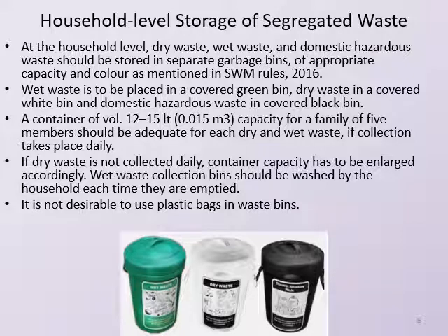So now first, household level storage of segregated waste. We should first consider what we are doing and what we should be doing at our household level. At household level, dry waste, wet waste and domestic hazardous waste should be stored in separate garbage bins, separate waste bins or separate dustbins of appropriate capacity and color as mentioned in Solid Waste Management Rules 2016.